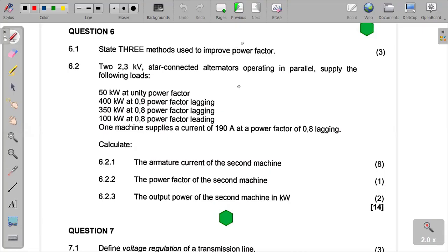Just out of interest, I might want to add on the phase advancers to say what exactly they are. These are AC exciters. It's actually an AC exciter mounted on the shaft of an induction motor connected to the motor's rotor circuit, so as to help improve the power factor. That's how it is connected in the circuit.